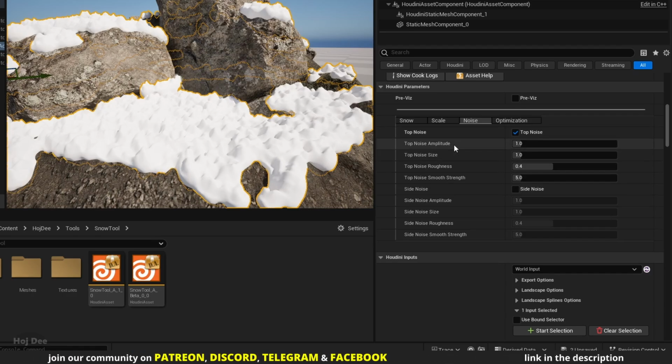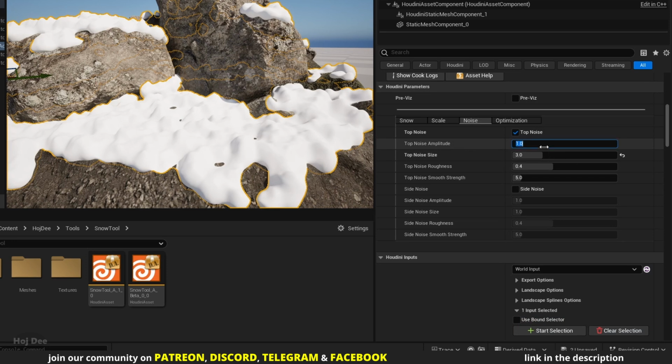Amplitude is the intensity of the noise. Size controls the size, and roughness and smooth strength both control the smoothness of the noise. Let's set the size to something like 3 and the amplitude to 0.5. Now we can see its effect by disabling and enabling the top noise.